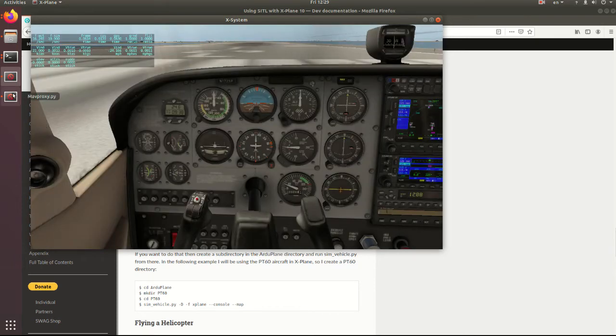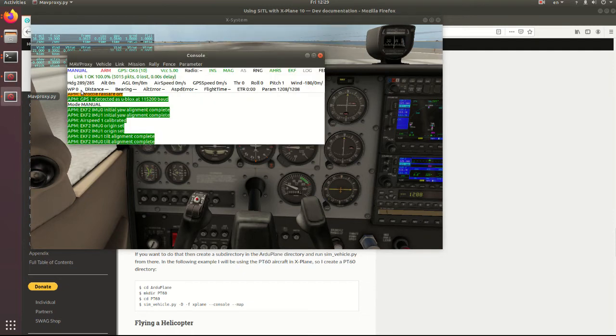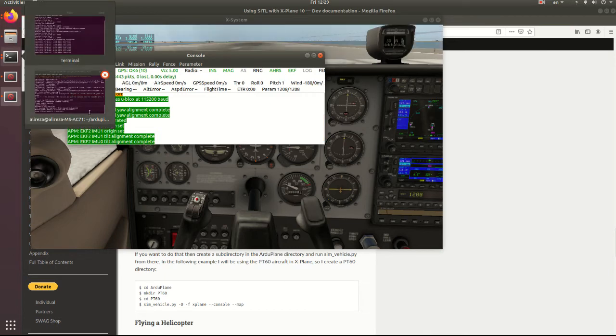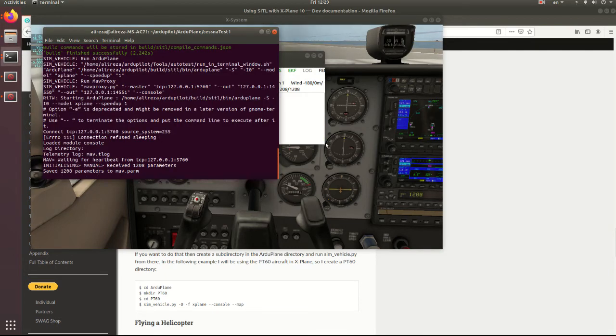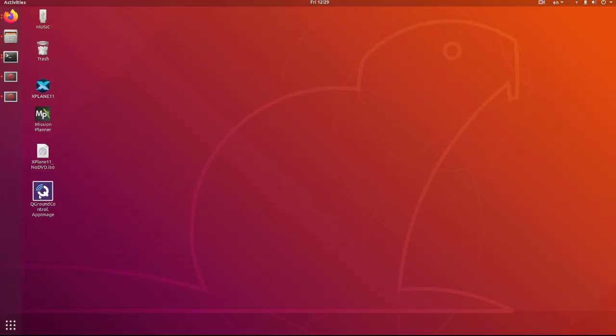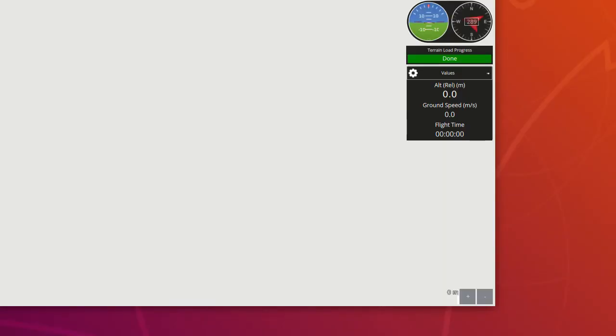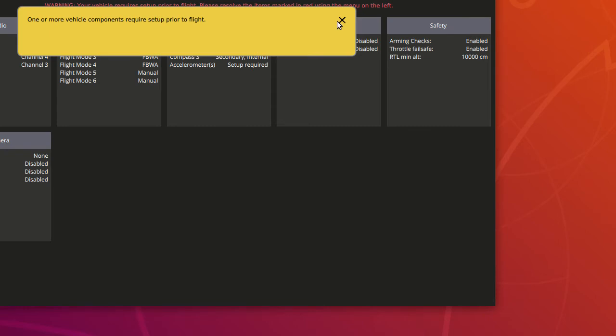Okay, now we can use MAVProxy to send commands, or we use QGroundControl to connect to our PX4 simulation. Just like our last videos, I'm going to run QGroundControl or any other simulator that you like, APM Planner, Mission Planner, Droid, I guess. Right now my system is not very fast, so it takes a little while for QGround to load up. Okay, here's QGround, and it automatically connects to our simulator because we have already set the UDP connection.